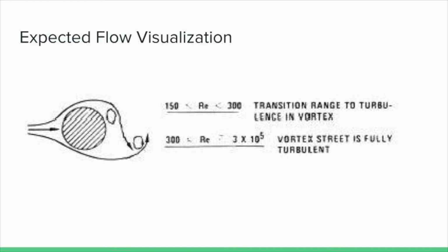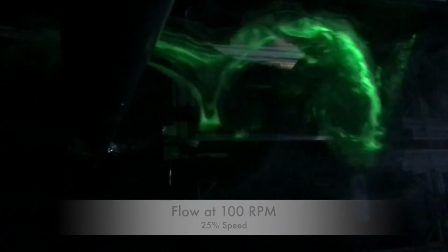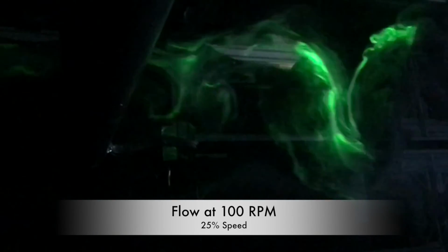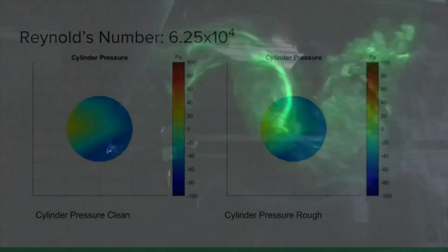All of the Reynolds numbers used fell into this range, so the same flow visualization was expected throughout the experiment, but the degrees of turbulence will increase with the rising Reynolds number. By analyzing the slow motion footage, it was found that the vortex shedding frequency is 6.4 Hz.